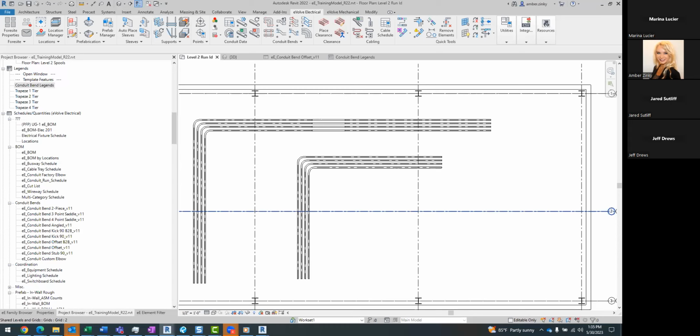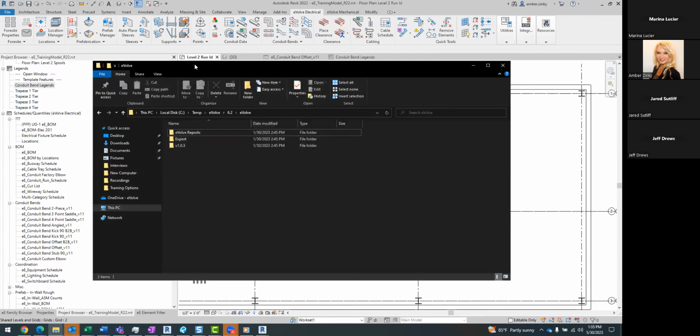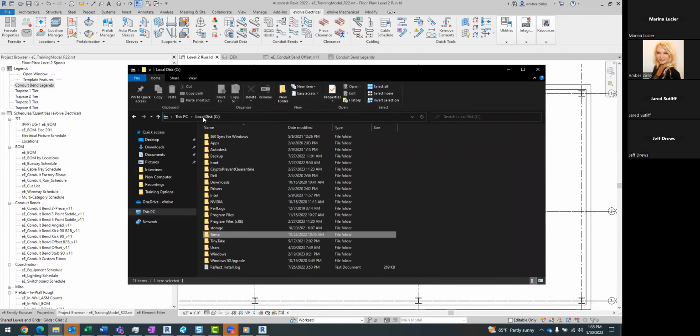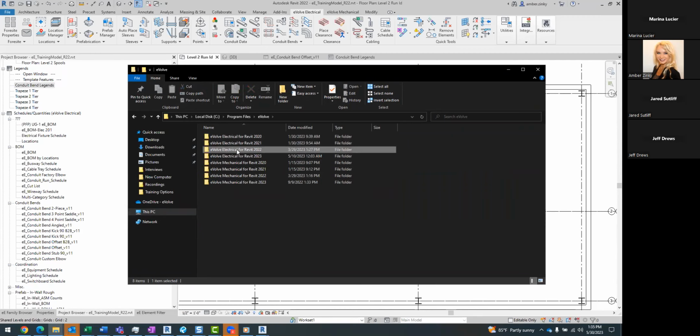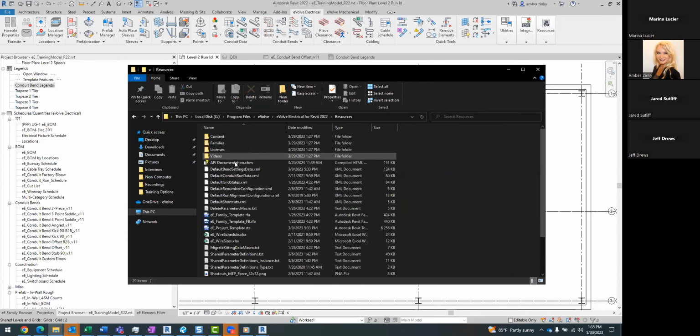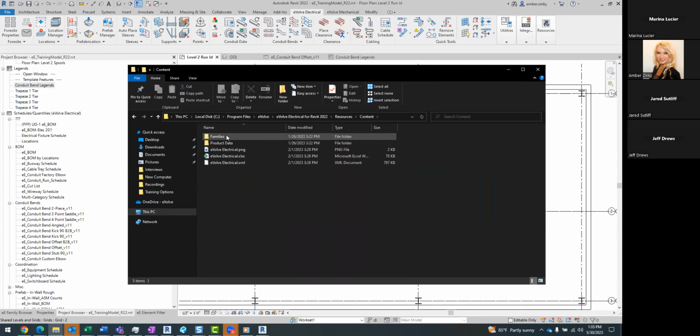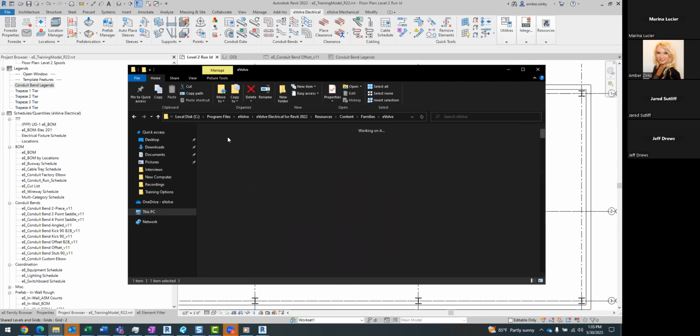So you learn placing elements, adjusting elements, editing families, why it's important to duplicate type, the difference between type and instance parameters, and being able to work with and utilize the different views, what they mean, sheets. So we get you going from 0 to, I'd say, I don't know what you say, Jeff, about 75 in the first 24 hours.